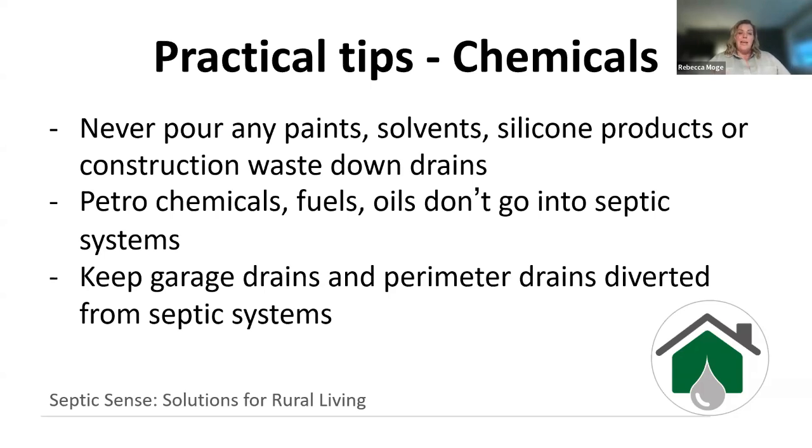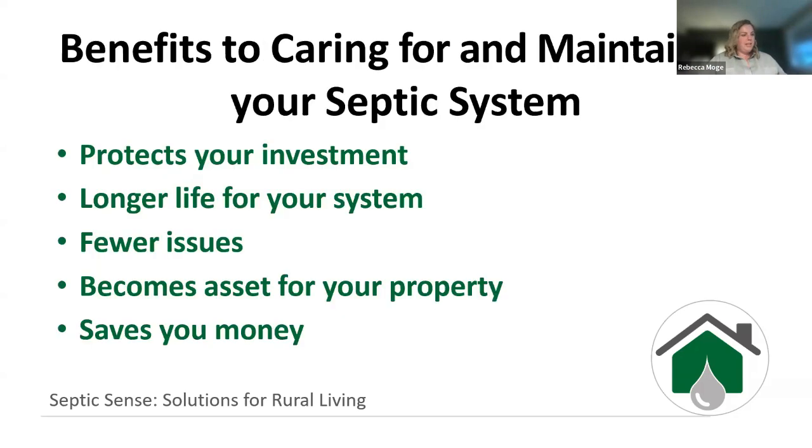Our garage drains and perimeter drains, we don't want going into the septic system. Not only is it adding, from the garage anyways, possibly the oils and things that we don't want in there, and overloading the system with all the surface drainage. But if our system backs up, it's going to back up into those, and then the entire perimeter of your house will have sewage and you can't clean that out. So again, those are things that we're not adding into the system. They are dealt with and managed separately.